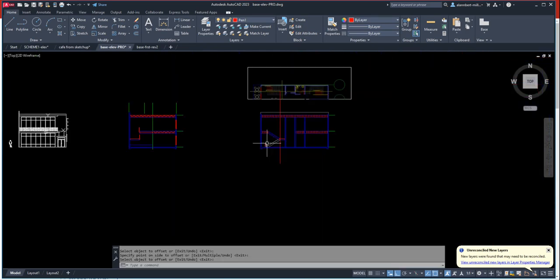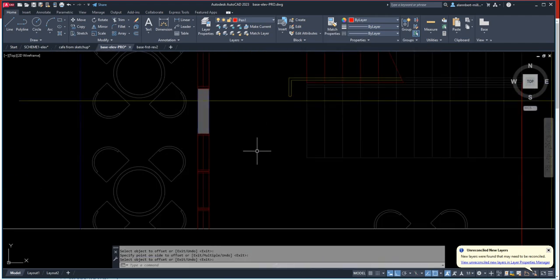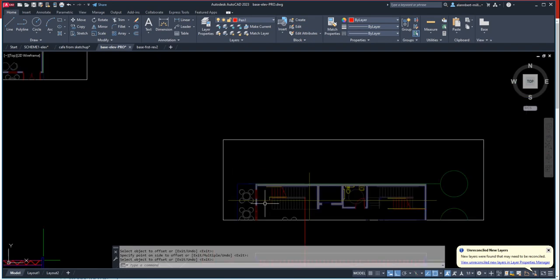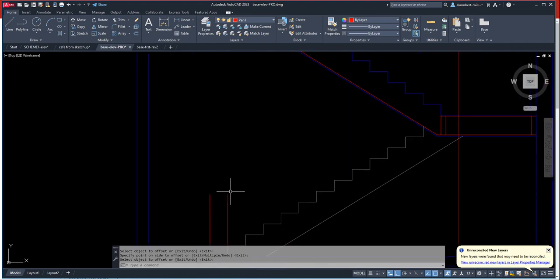Now, because the direction of the stair is not going direct here, I can turn this handrail here. But some jurisdictions don't want that. They still want the stair at the bottom to go straight. Some jurisdictions will allow you to do this because the interpretation is people coming down will not go straight, will have to turn, so you can turn the handrail toward the direction of the stair, and the stair turns this direction. But sometimes each jurisdiction, county, whatever, has a different interpretation.